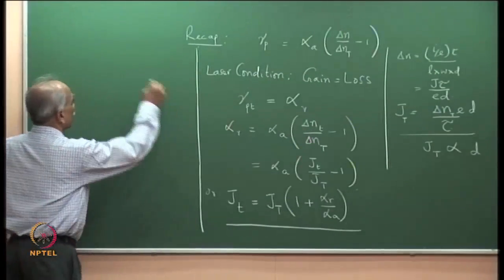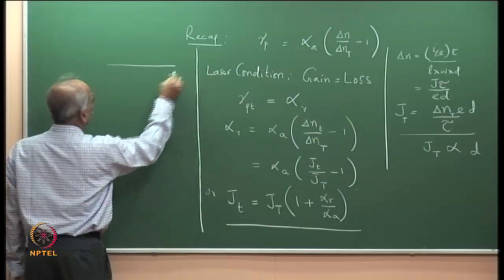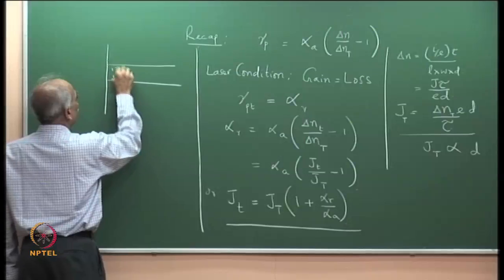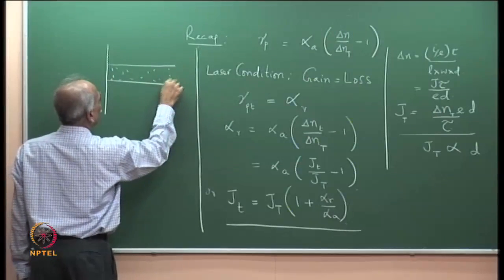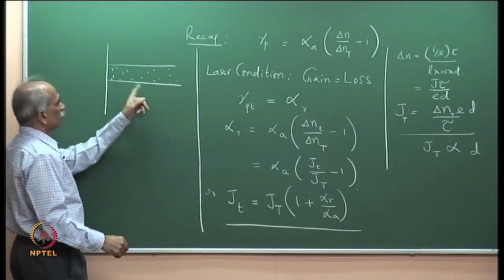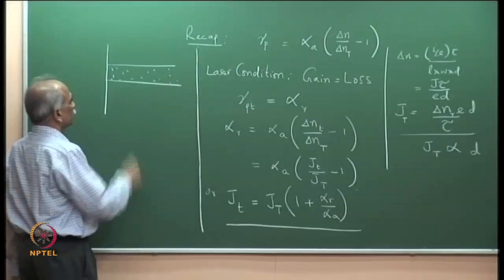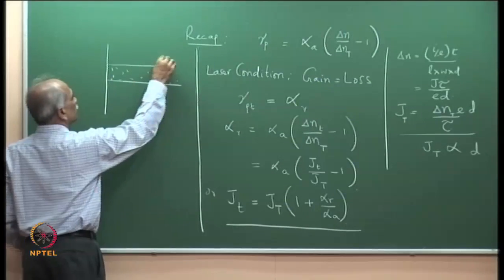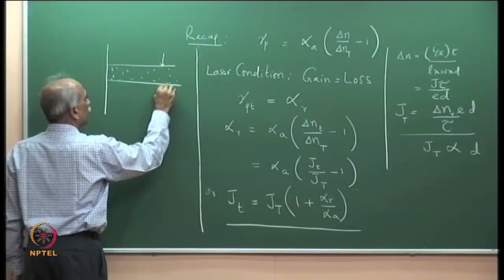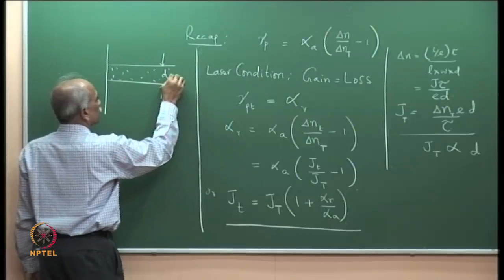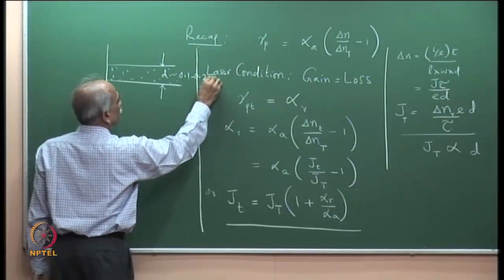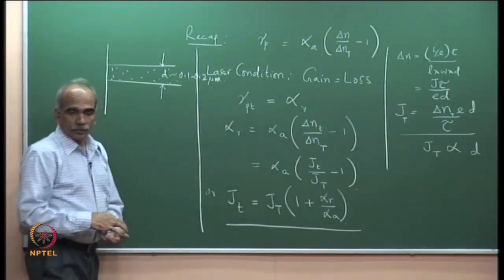In the case of semiconductor lasers, we have an optical waveguide there. The active medium, I am showing only a portion of the semiconductor laser. So, this goes down to cladding layers and then substrate and so on. I have just zoomed this active layer. This is that D, which for a double heterostructure is about 0.1 to 0.2 micrometer.